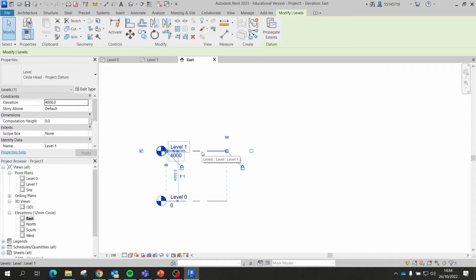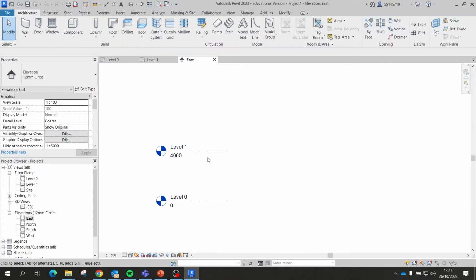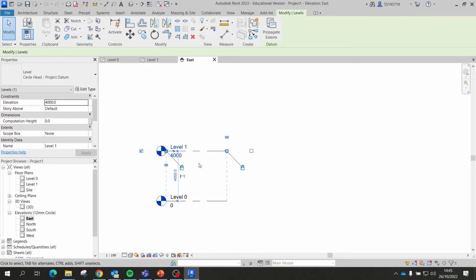So Revit works in millimeters, so careful. I mean, this is a good notion to keep in mind, especially if you're working between different software. So Revit works in millimeters. You see the level is at 4,000 millimeters, so 4 meters. But once again, it's something that we can change if we want. So I can come in here, open this little dialog window with the text and say this will be instead at 5 meters, and the level will adapt, right?